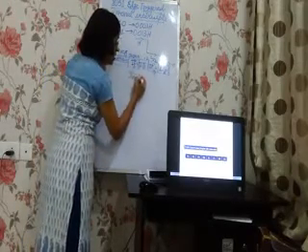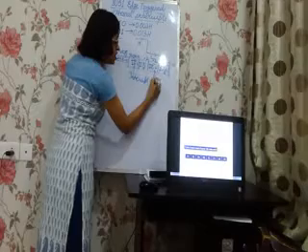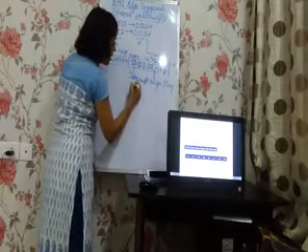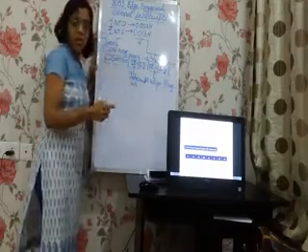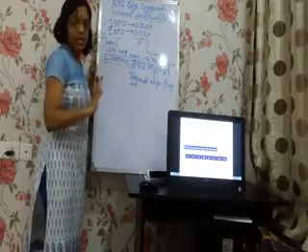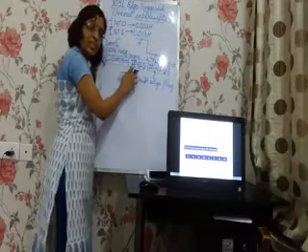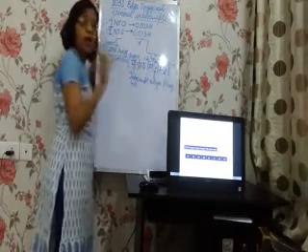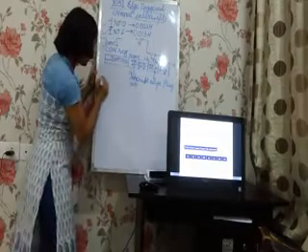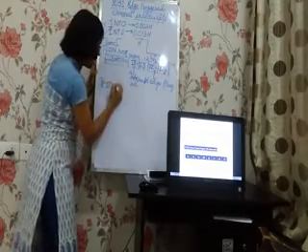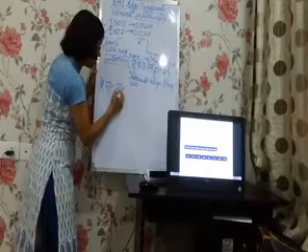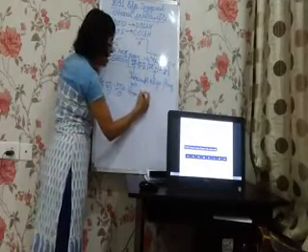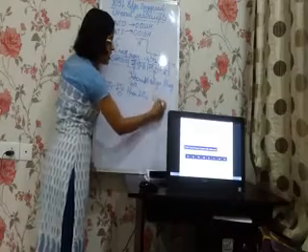Interrupt edge flag control bits, or interrupt edge flag bits. These are activated only and only if IT1 and IT0 are 1-1. If IT1 and IT0 are both 0, then for that case IE1 and IE0 are don't care.